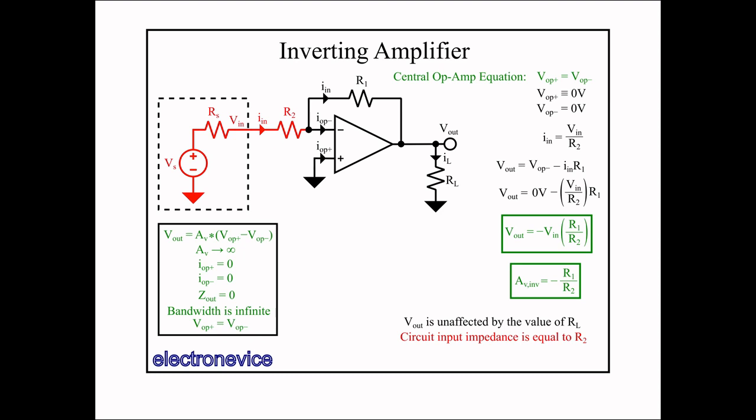Since a summing circuit can only add signals together in a sum, if you wish to subtract a signal from another, you have to invert one before inputting it into the summing circuit. We will discuss summing circuits in a later video. The gain magnitude is only slightly different from the non-inverting gain magnitude, off by 1. There is one useful difference here, though. The non-inverting gain magnitude cannot be less than 1, but the inverting gain magnitude can be less than 1.